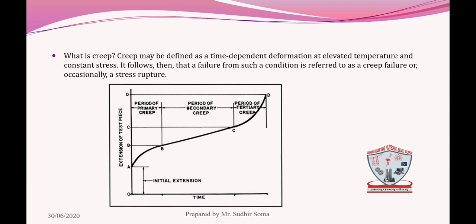You see the figure, if a stress below the proportional limit is applied on initial tension, an elastic strain will occur immediately upon application of the load, and regardless of the duration of application, the strain will remain constant. So this is the concept of creep strain and creep curve.